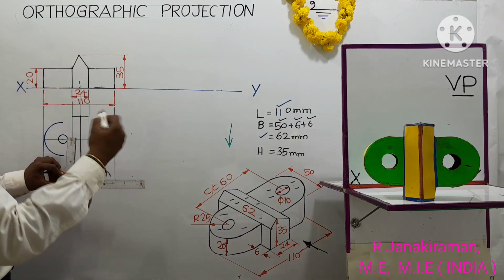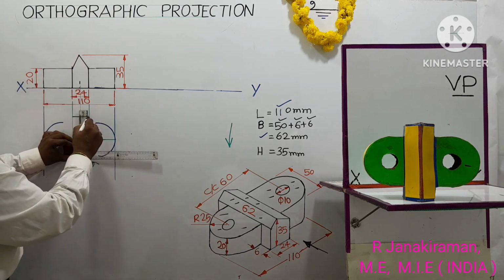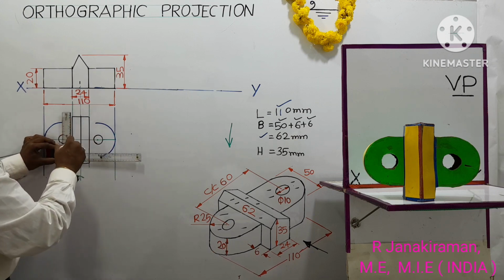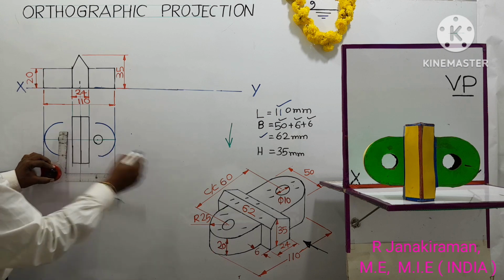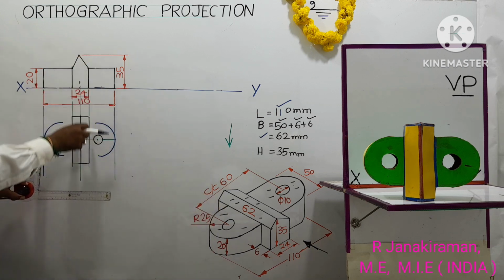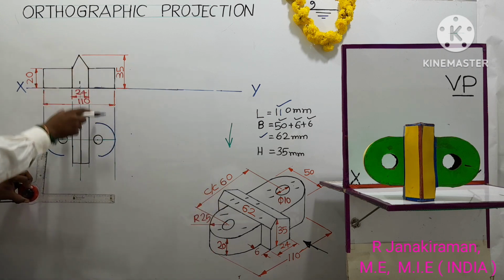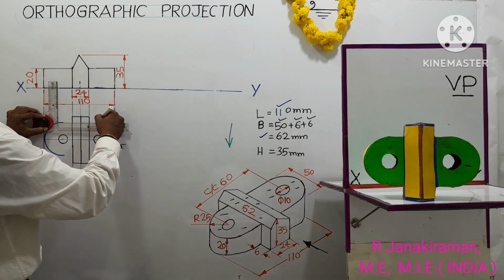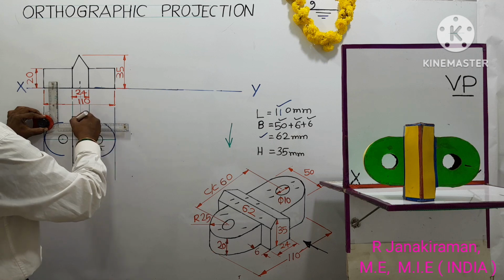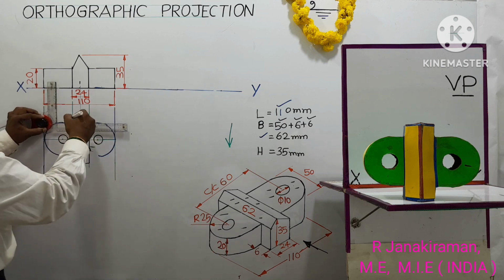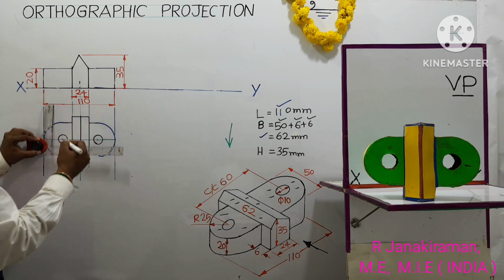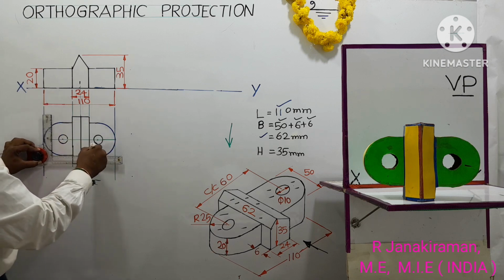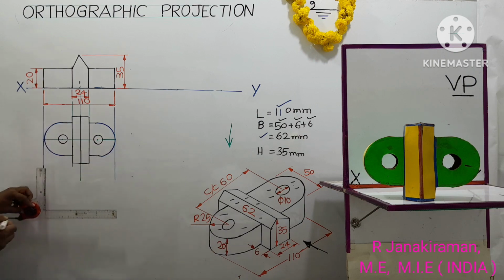And the right side yellow portion forms a rectangle. This is that, and on the left hand side one rectangle. This linear distance is not given in the diagram. It's projected from the previous front view. Exactly, the front view below the top view diagram will come. That you have to understand. Then extend these two semicircles, connected by an HB pencil as an object line showing the top edge. Similarly on the lower portion. So the view obtained is called a top view.